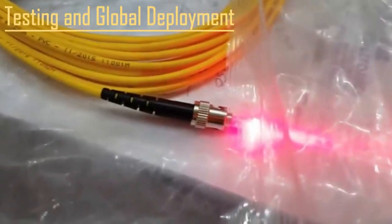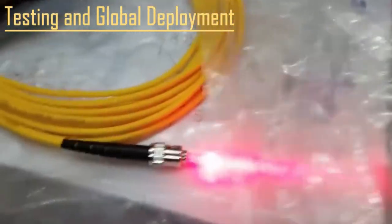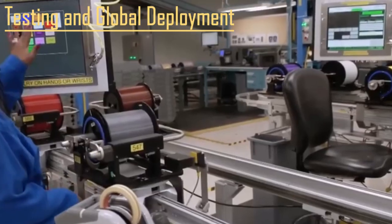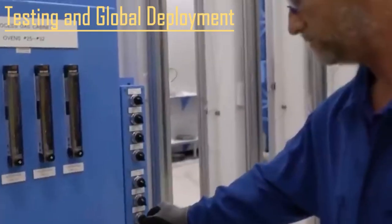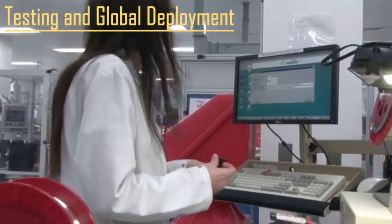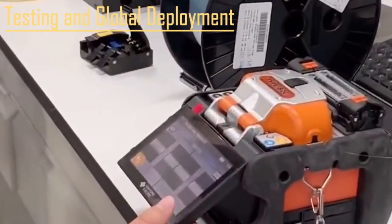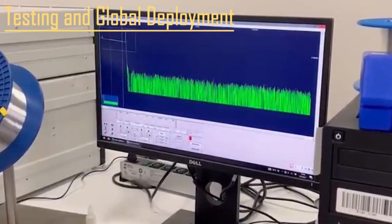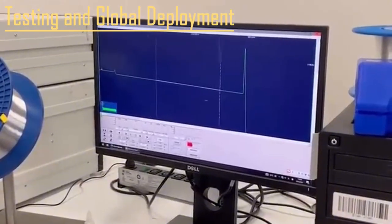The most critical step is full-length testing. Engineers connect both ends of the cable to optical transmitters and receivers, sending data, video, voice, and network traffic continuously for hours. The cable is only considered ready if the signal passes through the entire length without packet loss, distortion, or abnormal attenuation.